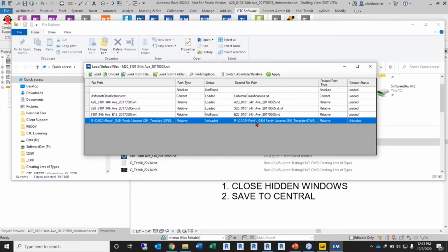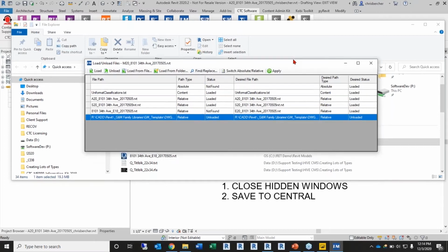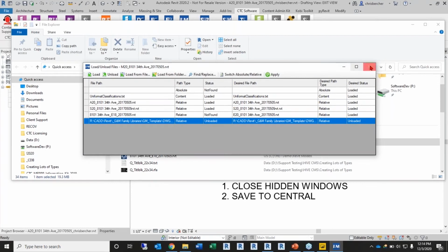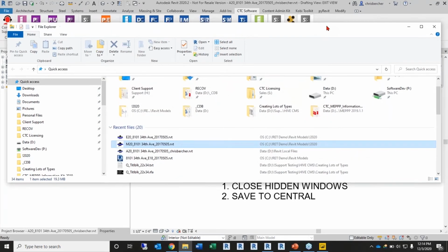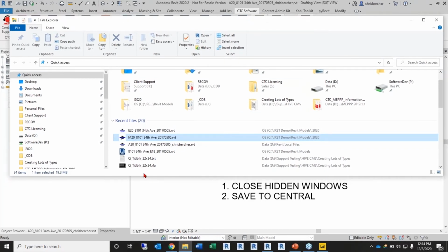Example, say this AutoCAD file, or the Revit files for that matter, potentially. I want to make sure that they are set to be relative paths so that when I bundle everything up and send it off, everything comes in together already. So I could switch files to be a relative path if they weren't, and make sure that everything functioned correctly once it was passed along. So oftentimes that's how I use the right-click manage links option that we've provided.